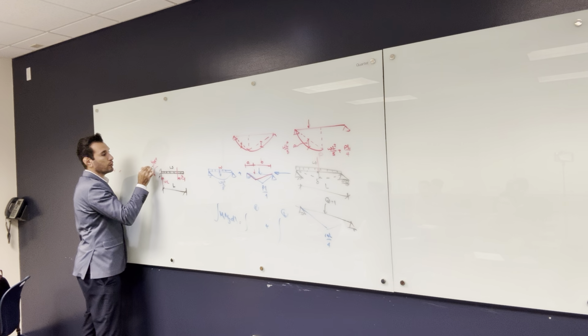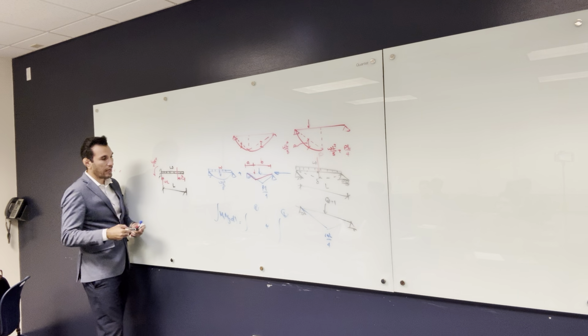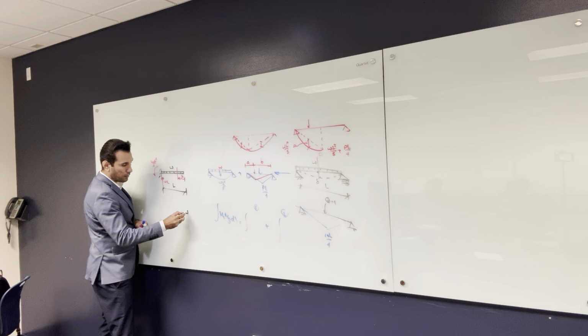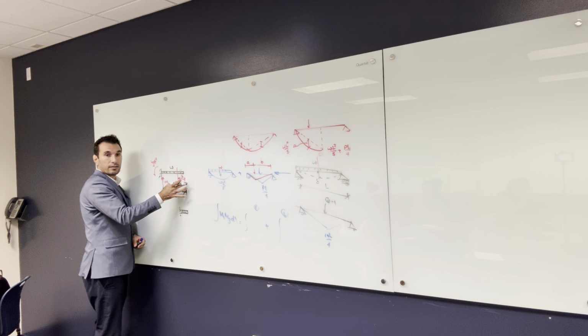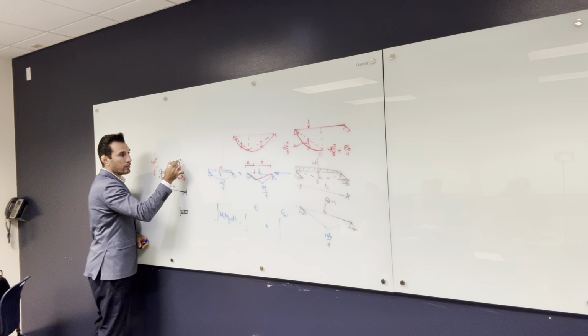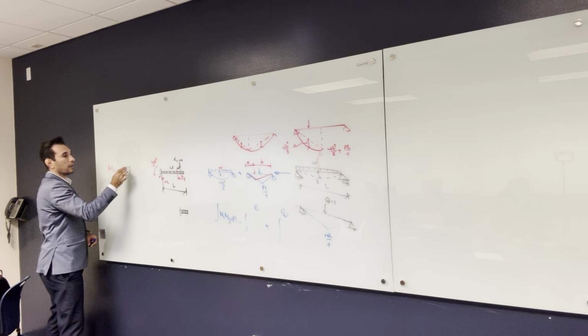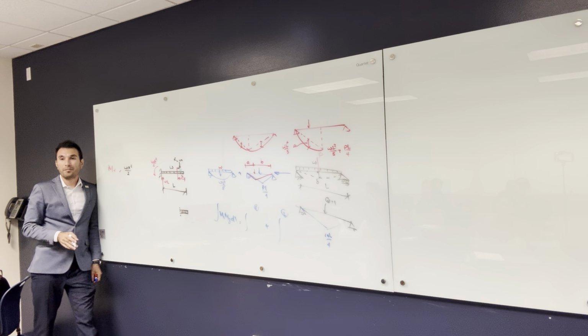So to find the bending moment at any section X, you will take this cross section out here, something like this, and then the bending moment at section X is going to be equal to this piece is X and this is W. So you are going to have here MX is equal to W. The whole load WX is affecting in the middle, so the resultant is equal to WX, this is R, and it's at distance X over 2, so the bending moment at this section is WX squared over 2, that's the MX.